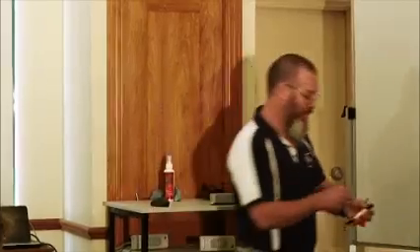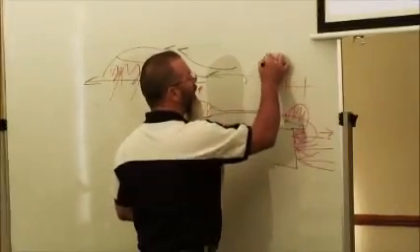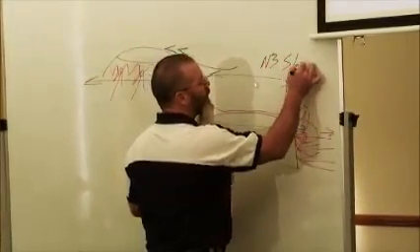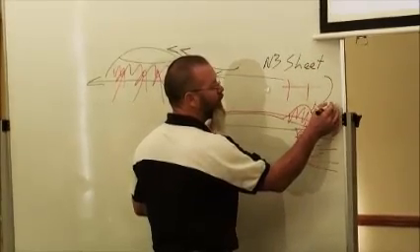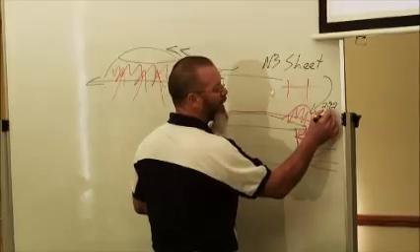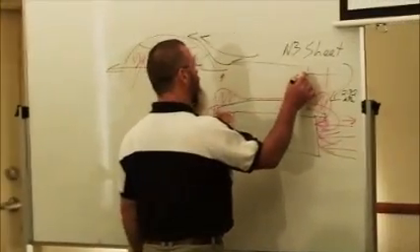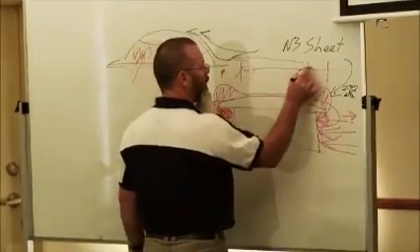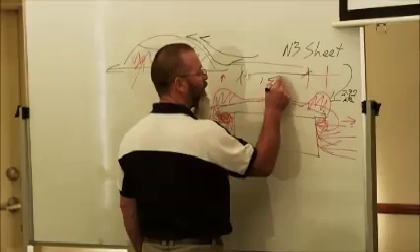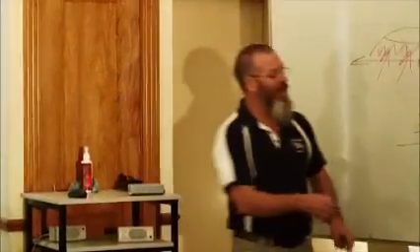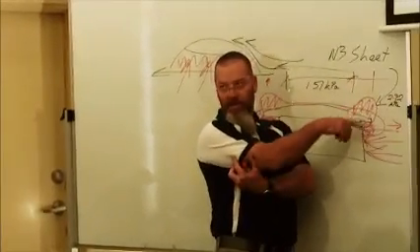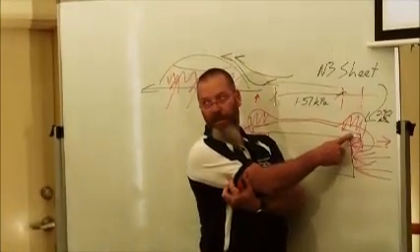Yet pressure on the edge of the roof is 2.92 at this point. So N3 sheet. On the edges, just here, it's 2.92, and that's kPa, little k, capital P, little a. And in the general area, it's 1.57. So this area from here to here, the pressure is 1.57 kPa. And you can thank Dr. Bernoulli for that.